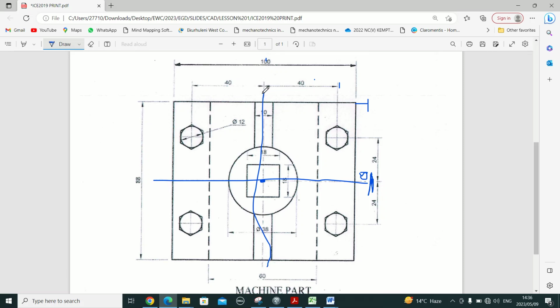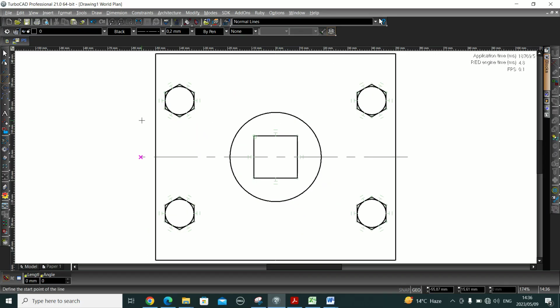Let us start it there. Again, we are adding 5 here. We are using that 44. 44 ends here, plus 5. So 44 plus 5 is 49. For y, x is 0. So press tab. X will be highlighted, x is 0, y is positive 49. Press enter. So our line is starting somewhere there.